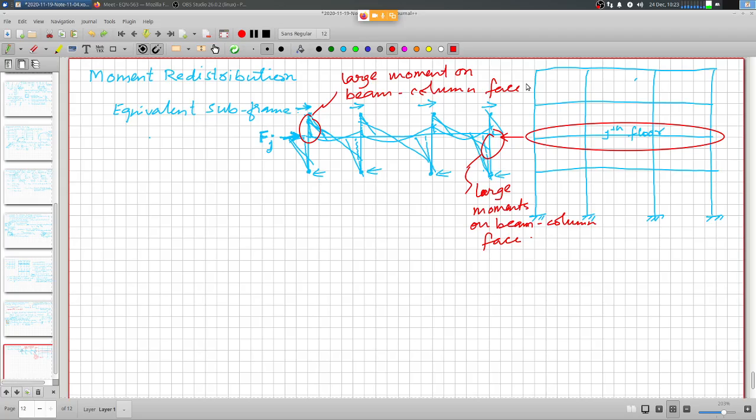Even the gravity load forces would be smaller when real design level earthquake effects are to be accounted for. That's why whenever you have the earthquake load in the load combination, the partial load factor on the dead load and imposed load is reduced somewhat to account for the fact that the stiffness is reduced, and therefore the forces are going to be reduced on the section.